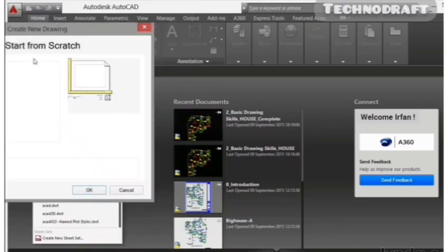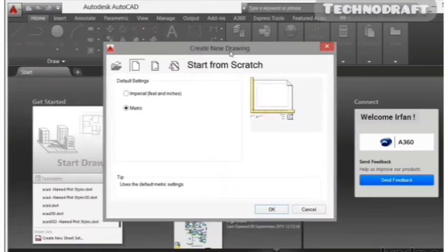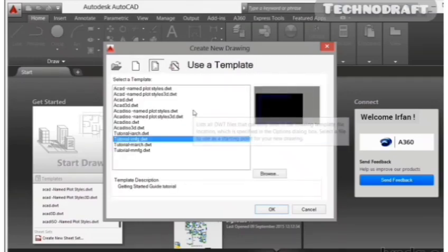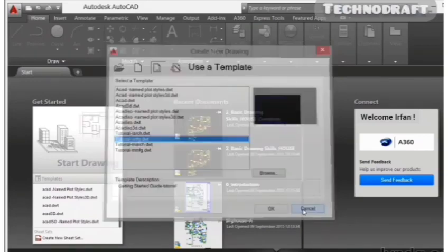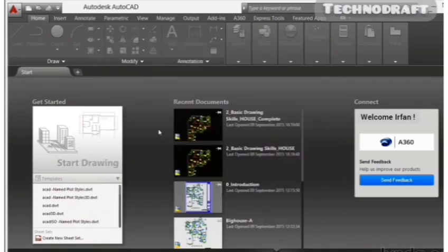And if I click on New, that will take me to the folder or perhaps the startup menu here as well, which allows me to find particular AutoCAD template files, DWT. I will just click on Cancel there now. Close that down. So that's just using the application menu.